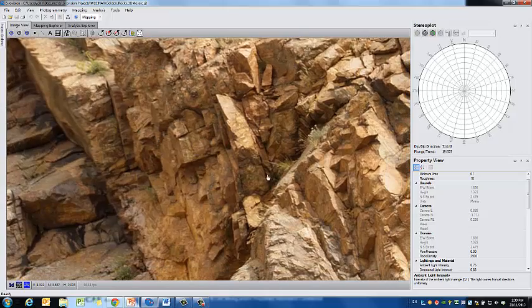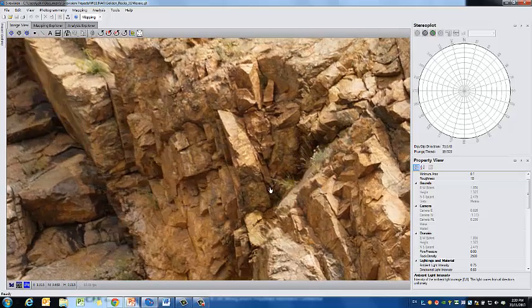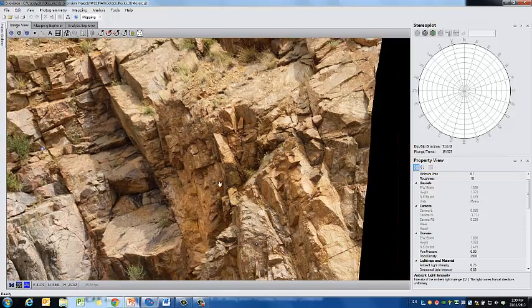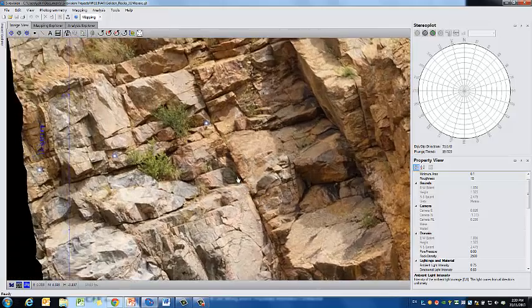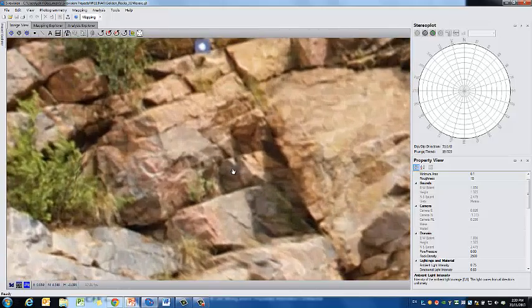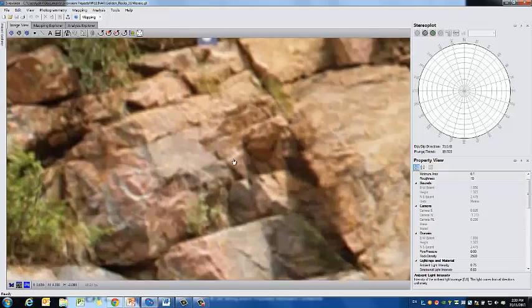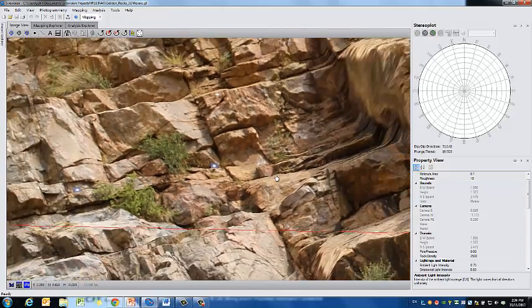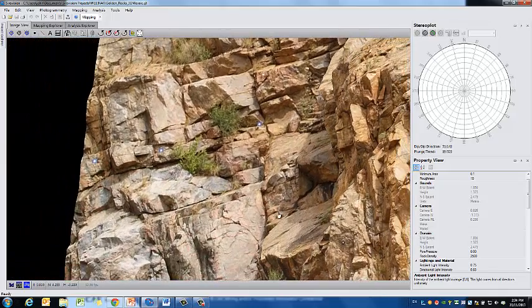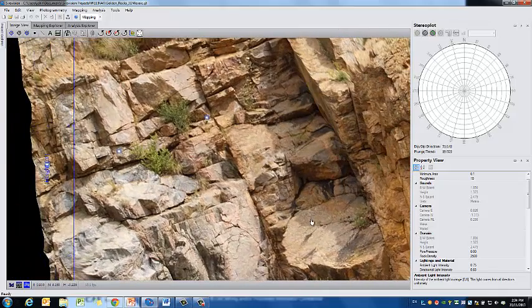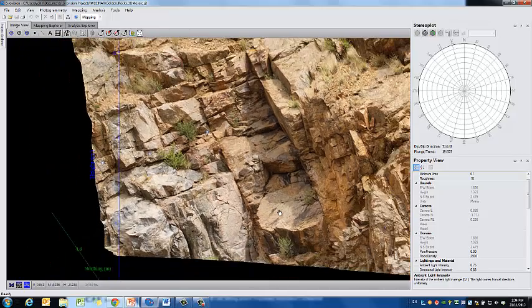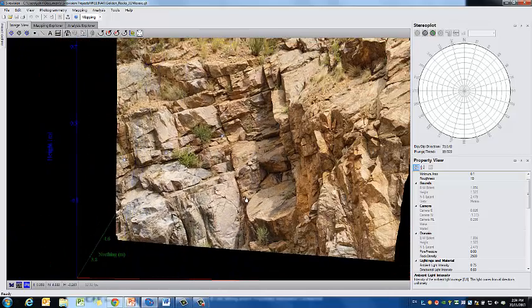The beauty of photogrammetry is that you can change lenses. It's very flexible. You can get into any areas in the pit, so you can basically map everything in the pit using a photogrammetry system like Sirovision. And this is the kind of detail that you're getting with that kind of lens, with a Nikon 24mm lens. So you can see that it's pretty detailed. It can be as detailed as you actually require the system to be. So in this case, we've got a single 3D image.